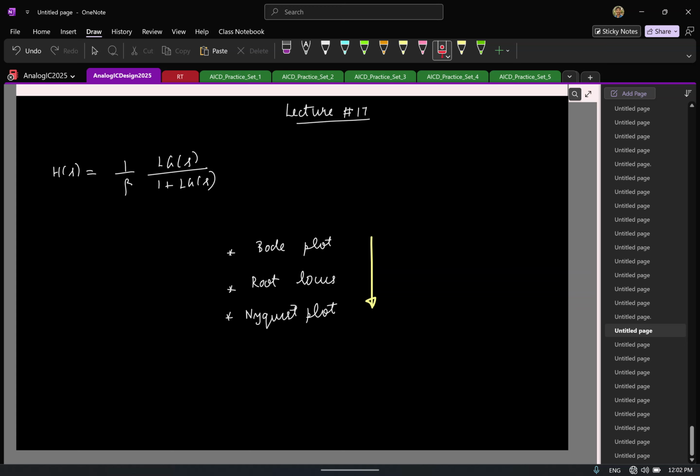So root locus and Nyquist plot give exact information about closed loop stability. So we typically try to understand stability from either of these, and then translate that understanding to the Bode plot because it is much easier to plot Bode plots. Although traditionally this is done with the Nyquist plot, I usually take an alternate approach and prefer root locus, because if I were to explain the Nyquist plot, I should explain complex analysis, Cauchy's integral, number of encirclements this side, that side. So I'll skip all of that, and let's see how we can understand through root locus.